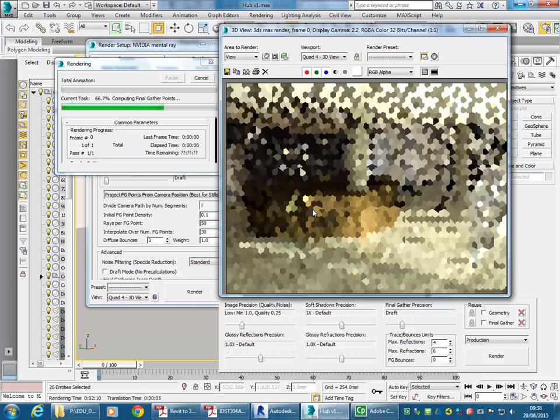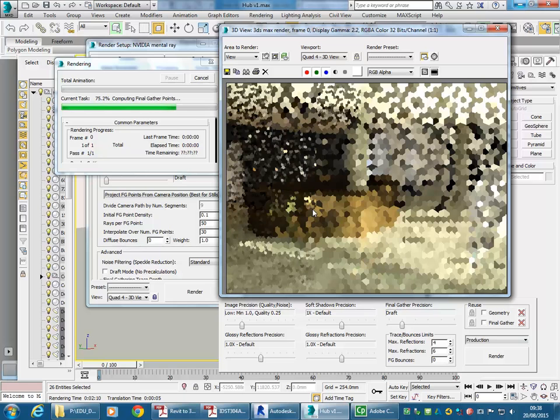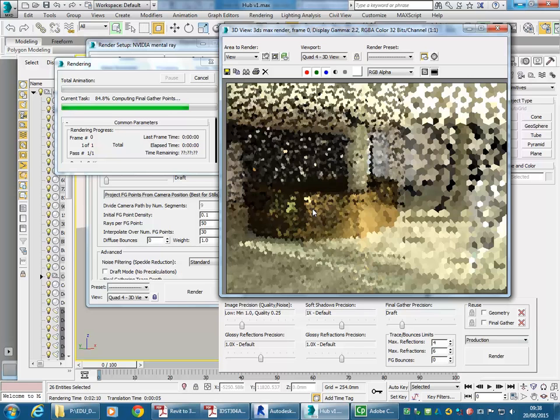And that's a huge advantage when you're rendering interiors and you're trying to get natural light to do most of the work. You often need to have extra bounce lighting. So even if it's just for that option, it's really worthwhile using Max to render instead of Revit, because with Revit it's very difficult to control that.